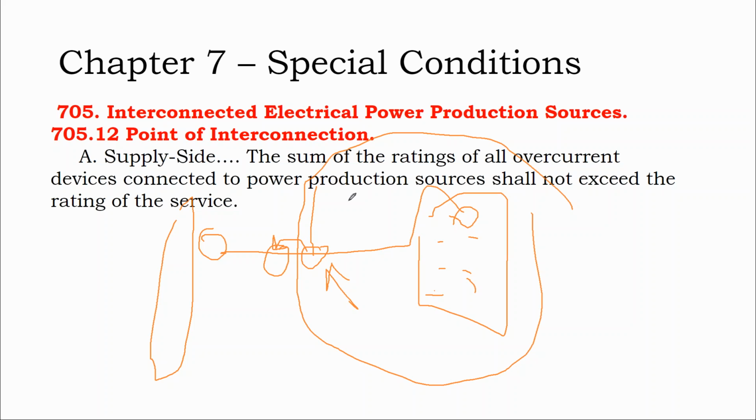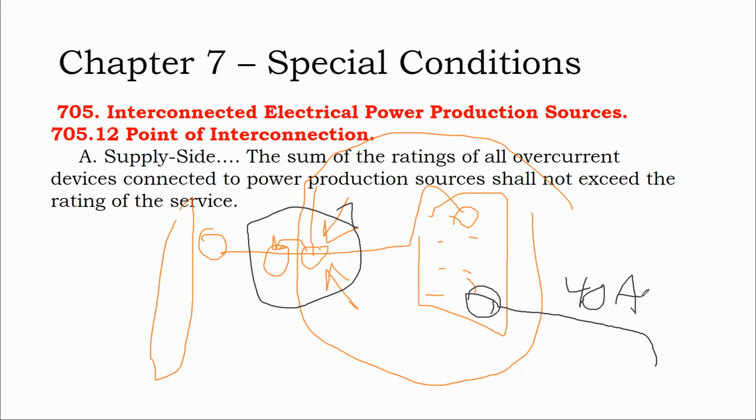You might want to put that switch right here, so that you can fully isolate the home from the grid. So if you're doing a supply side connection, I think you need to start thinking about automatic transfer switches for the whole house and start building the infrastructure for whole house backup. Maybe not doing everything today, but at least putting in the appropriate disconnects and switchgear when you're already working in that area. And sometimes it's easier just to keep it simple. For systems that are 40 amps or down, just land onto the service panel until you're ready to do something more ambitious.